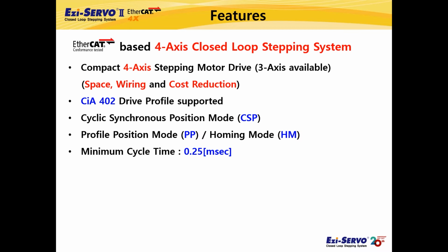And the minimum cycle time is the time it takes for the slave to receive, process, and respond to a packet. In general, the minimum cycle time of stepping motor drives on the market is 0.5 milliseconds, but FASTECH's product has a shorter minimum cycle time of 0.25 milliseconds.